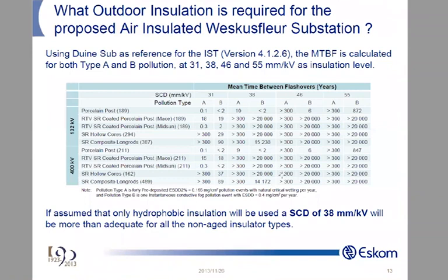You can use an EPDM, for instance. You just compensate for certain aspects, which means the area is going to increase, so you need to go for a longer creepage. So you need to increase L. You see again, rho L over A. And I think with that, I need to open up for questions, because otherwise I'm going to keep you here till breakfast. Are there any questions from you guys?